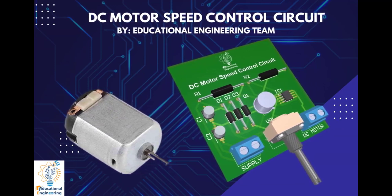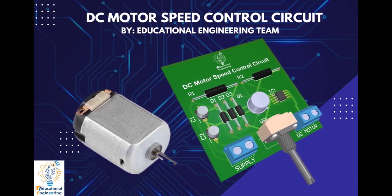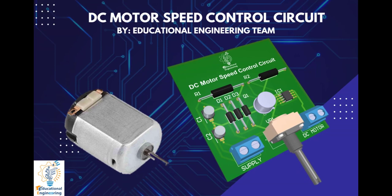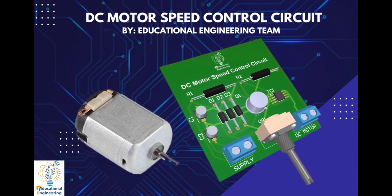This circuit uses a similar pulse width modulation technique to control motor speed and uses an IC 555 timer to generate the PWM signals. Modifying the resistance value of the variable resistor between its terminals will modify the duty cycle. So now, let's start designing it using Altium.